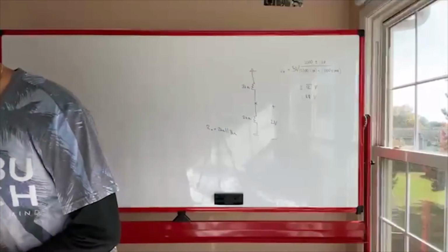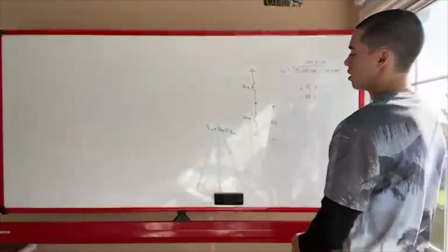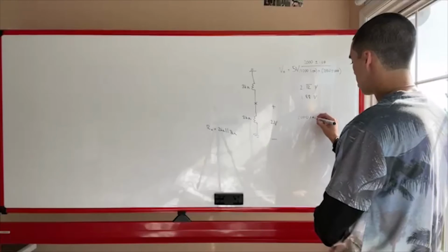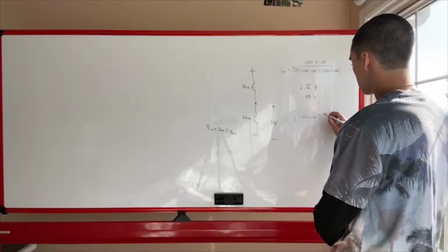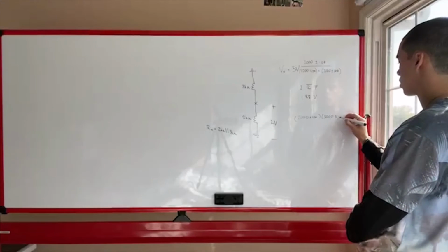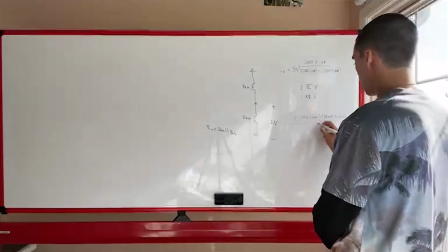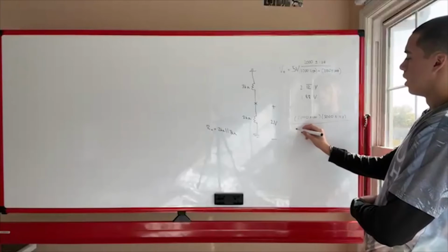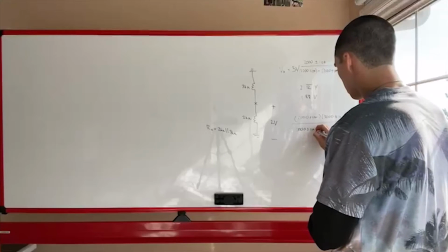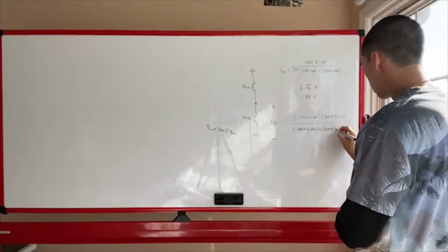What about the resistances that could be, right? So if that's the resistance thing, we could have 2000 plus or minus 100 times, this is the expression for the equivalent resistance with the tolerances. And I don't have it, so I'll have to do it. 2000 plus or minus 100 plus 3000 plus or minus 150.